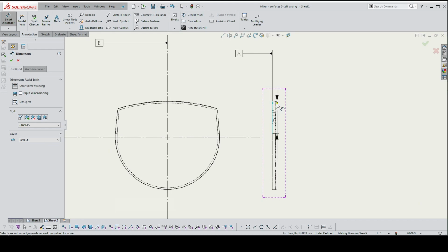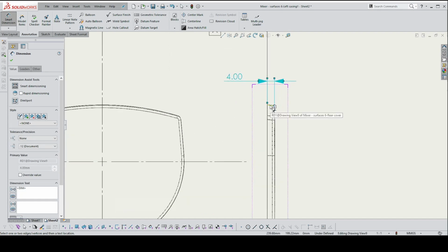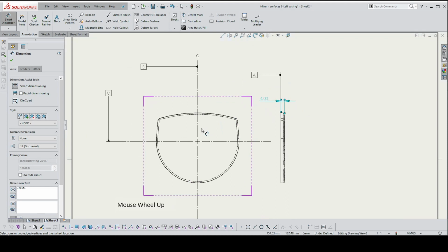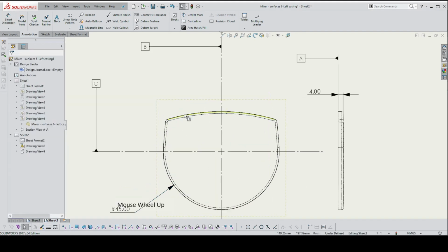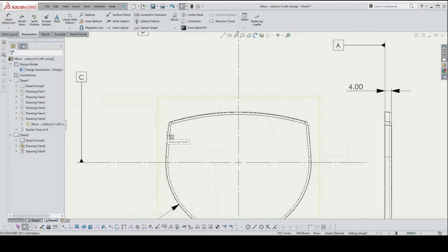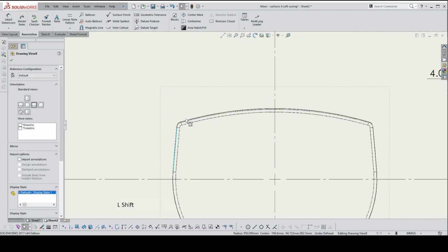And I'm not going to do the full dimensioning here because what you really need is a section view to show wall thicknesses, and in which you could then dimension things like tapers and so forth. So what I can do is, because I've got a center point, I can indicate that that is a radius of 45. What I need here is to be able to indicate the points where that plane and that plane meet, because fillets are things that you cannot use to position anything, and you should only indicate their size.